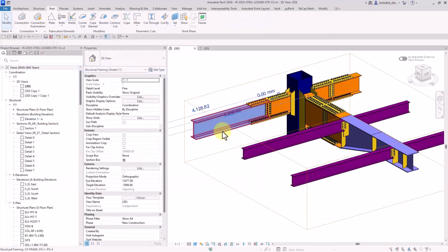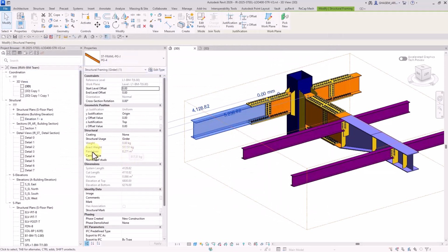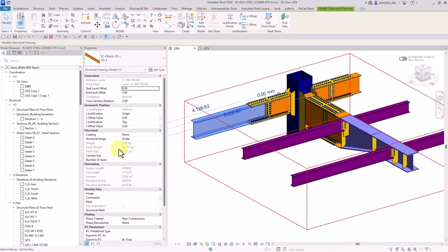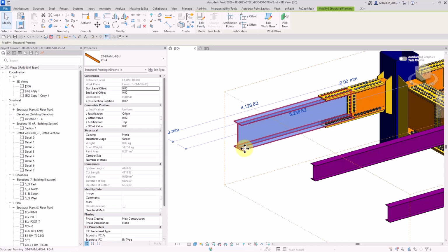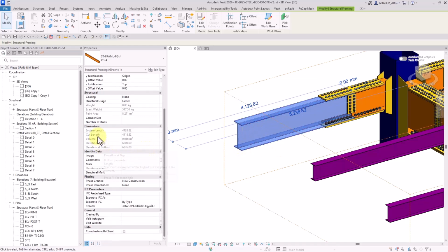Now, the parameters are calculated here. And we have the paint area here as well, guys. Now, this parameter, more precisely, paint area would be calculated through multiplying the perimeter by the cut length. Oh, and by the way, by cut length, we actually mean the effective remaining length here, okay?